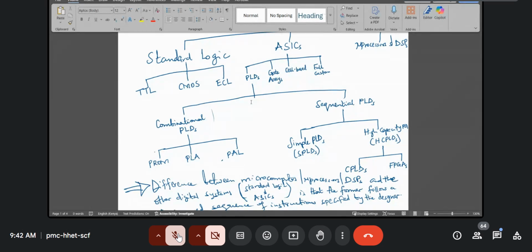Once that was done, I don't recall whether it was a one-time thing or reversible, but it was such a critical step that, from literature and from experienced persons, you are advised not to interfere with those bootloader fuses. You leave them as they are. So that was the closest I've come to blowing fuses. But I believe you can get more information on the same.